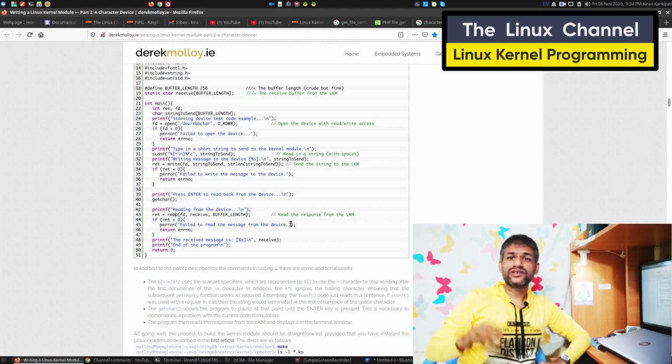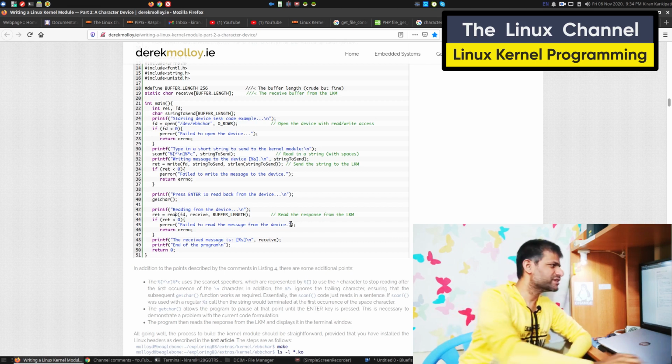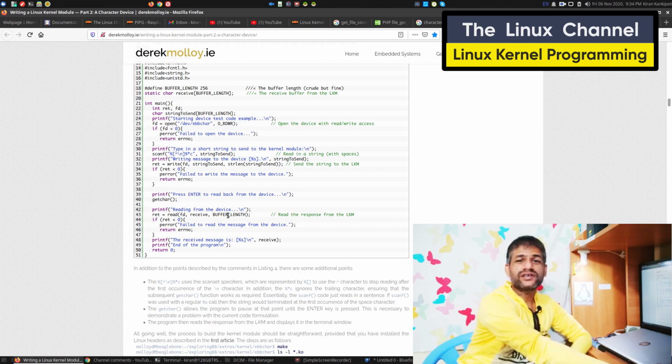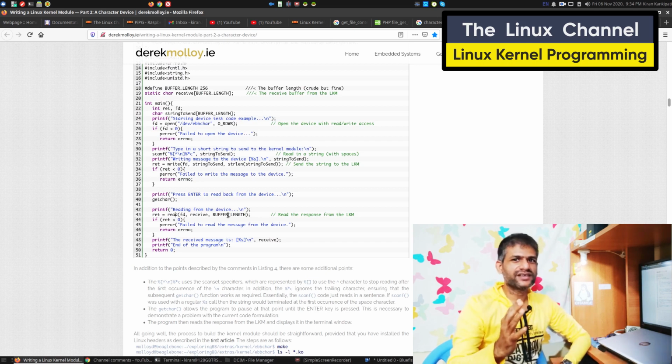Same thing, you can check the status of the GPIO pin by doing a read operation, you can set the status of the GPIO pin by doing a write operation, and you can do this continuously. See the advantages you get by phasing out the file system with a character driver.